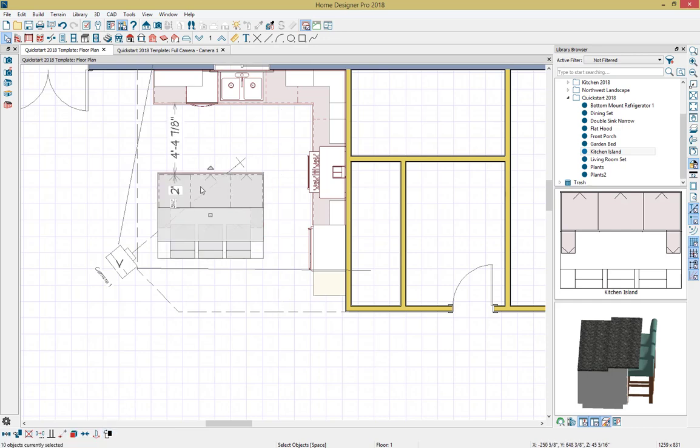which is down in our bottom toolbar. And then if you wanted to take your objects and form an architectural block, you can select them by holding Control and then select the Make Architectural Block, and they'll be grouped together. I'm going to go ahead and undo that. And then lastly, to add an item to your user library, you can press this button right here.